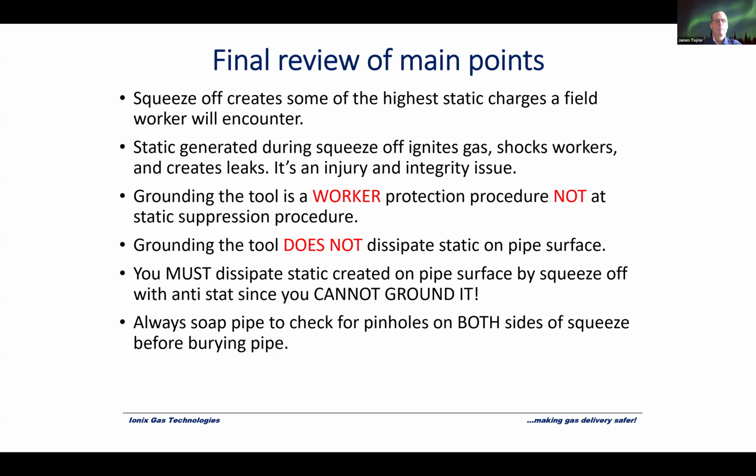Okay, well, thank you. So in review of my points then, squeeze off creates some of the highest static charges the field worker will encounter. And because of that, it ignites gas, it shocks, and it creates leaks. So it's an injury and integrity issue. It's important, as James said, to make sure your guys don't disable the grounding straps on the tool. It's worker protection, but it's not static suppression. Those are two separate issues.